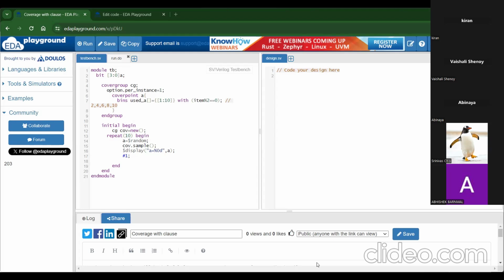Okay. And then at the coverage collector, we have the analysis export. Again, this information, if we want to send somewhere else, then we can use an analysis export. That way, we will just connect it in the environment. So if you see what exactly we have, the coverage collector should extend from the UVM subscriber.